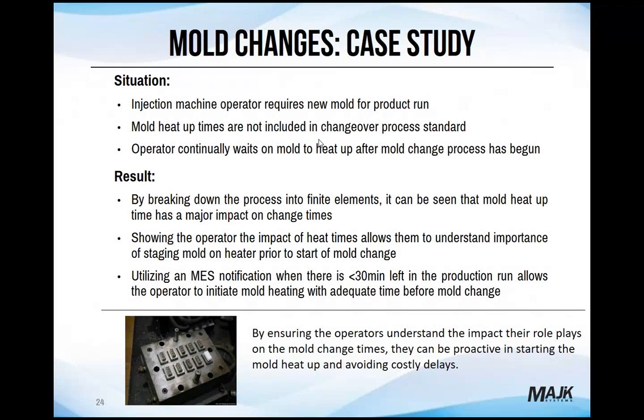So let's take a case study within the injection molding industry. What's our problem? We know that operators require a new mold for a production run, and each of these molds typically needs to be preheated before the changeover can happen. What we found was that the operator was continuously waiting on the heat up time because the mold process was started too late. So in order to fix this, you break down the process into its finite elements.